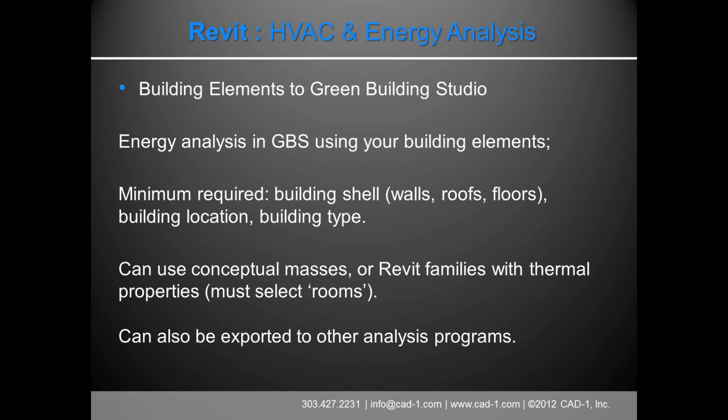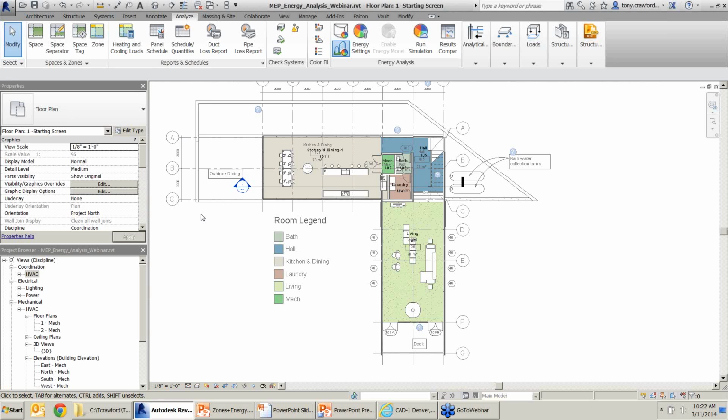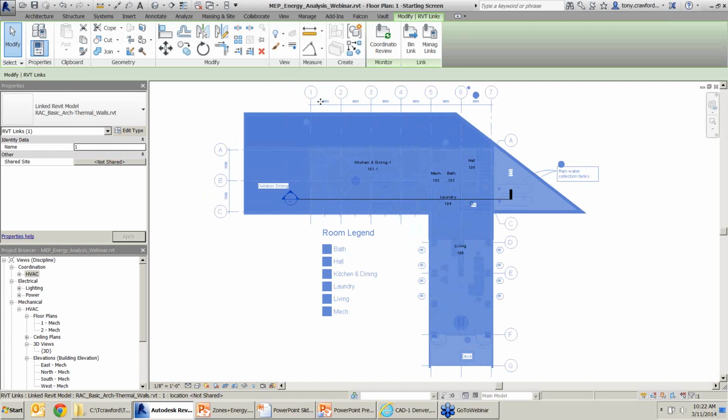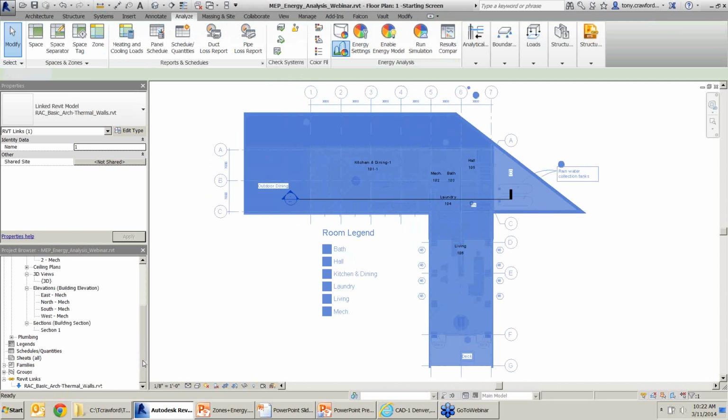I was going to add one more thing, and then I forgot what it was. Oh, I was going to add that this one you do have to do in a live model. The way I have this file set up in Revit, I started a blank file from the MEP template and linked in the architectural file like you would normally do. So I can't actually run that simulation from this file. It has to be live.